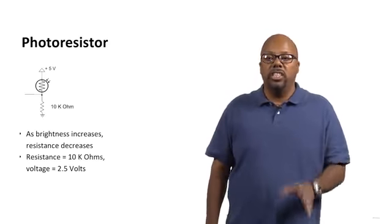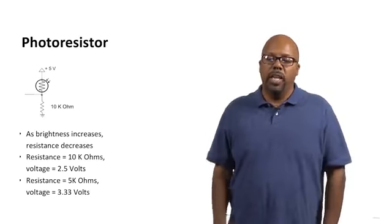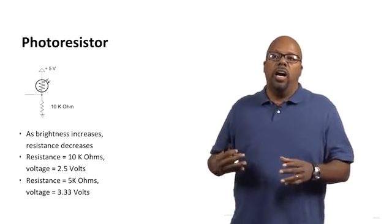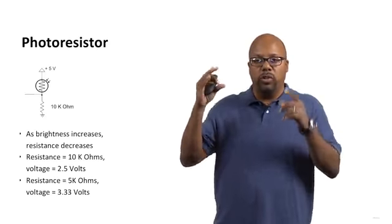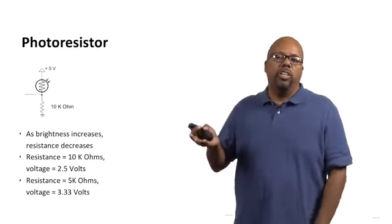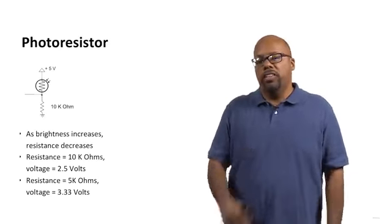But let's say the brightness changes, right? Let's say it gets brighter. Then the resistance goes down. So now the resistance of the photoresistor is only 5 kilo ohms. Now when that happens, you've got a smaller resistor on top and still the big 10 kilo ohm resistor on the bottom, right? So since there's less resistance on top, there's going to be less voltage drop, less voltage difference across the top resistor. So now the voltage that we measure in between those two resistors is going to be higher, 3.3 volts, because the voltage is disproportionately across the bottom resistor, since it's bigger relative to the top.